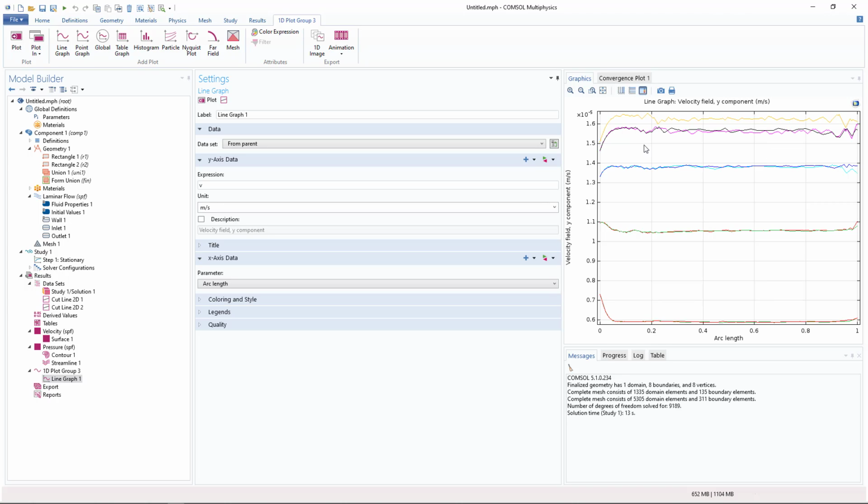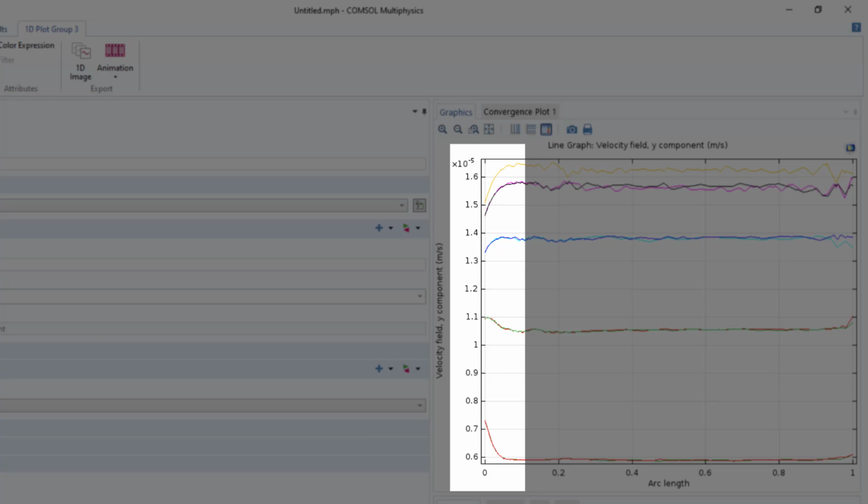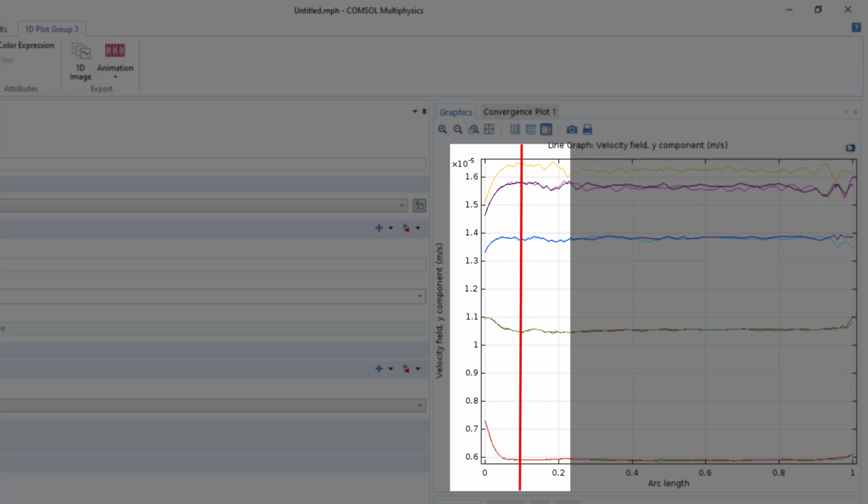where the steady state velocity is different, ranging from 0 at the walls to the max velocity at the center line of the gap. This graph shows that the velocities are changing rapidly within the first 3 or 4 centimeters from the entrance to the narrow gap, some of them increasing and some of them decreasing, but around 5 or 6 centimeters in, they reach a local maximum or minimum where the velocities have overshot their steady state values slightly.